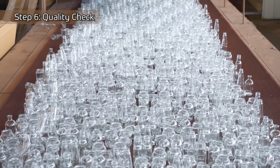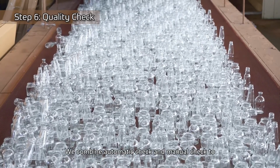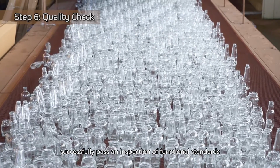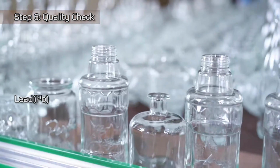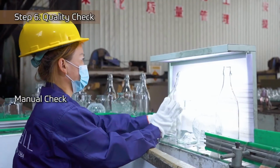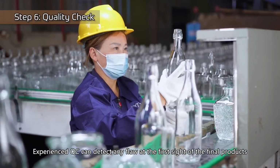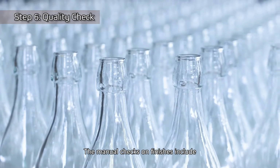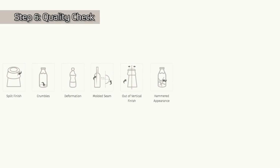Step 6. Quality check. We combine automatic check and manual check to make sure that the glass bottles successfully pass an inspection of functional standards. Experienced QC can detect any flaw at first sight of the final products. The manual checks on finishes include split finish, crumbles, deformation, molded seam, out of vertical finish, hammered appearance, thin walls, blisters, cord.